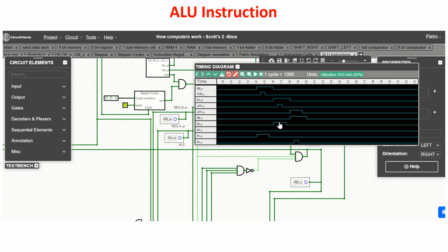And when we put the second operand on the bus, the ALU has both operands at its inputs, and so we can perform the operation straight away, because it is a combinational circuit and it doesn't need any clock. So immediately the result is on the output of the ALU, and we give a set pulse to the accumulator, always in the fifth step. So at the end of the fifth step, the accumulator contains the result of the operation.